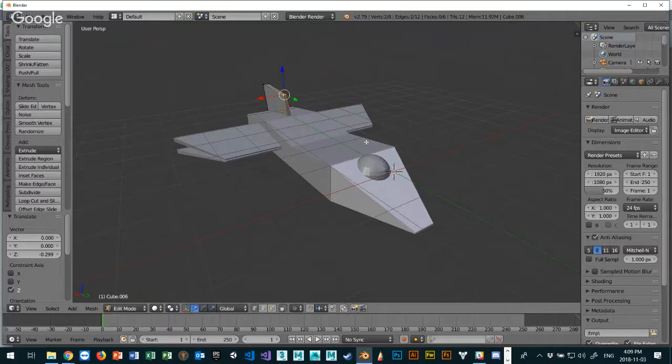All right, so far we've learned how to navigate in Blender. We've learned how to move things around by pressing the G key for translate or right-clicking and dragging. We've also learned how to go from object mode to edit mode, and we've described that edit mode is like editing the container that is the object itself, and inside that object container there is a primitive object called a cube or a sphere or whatever it is.